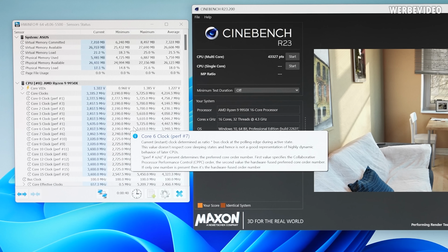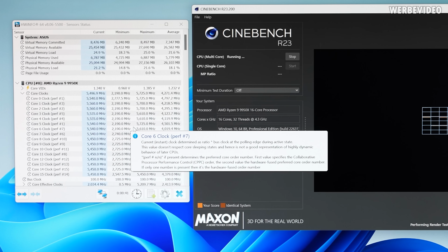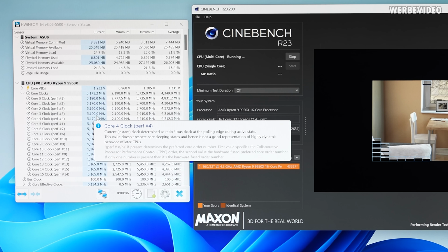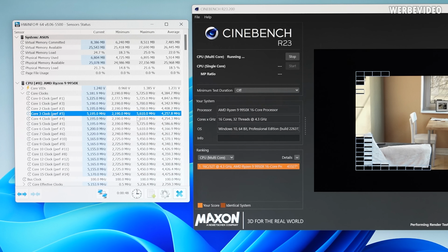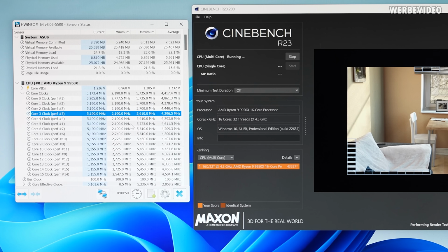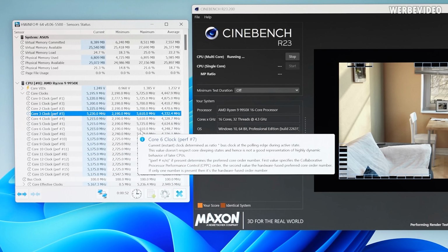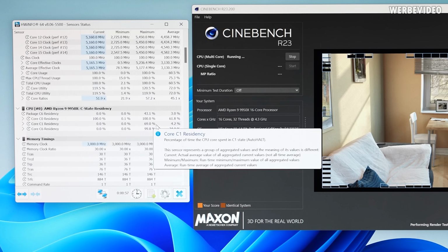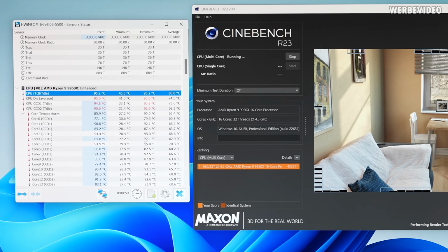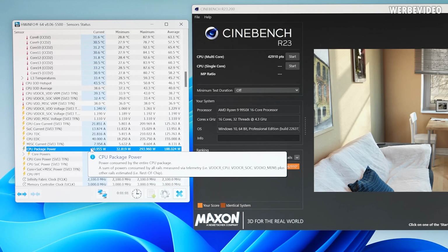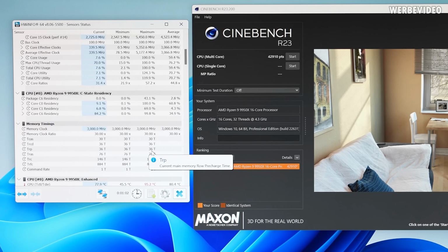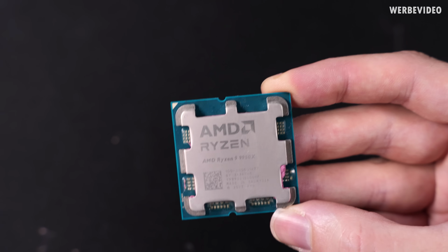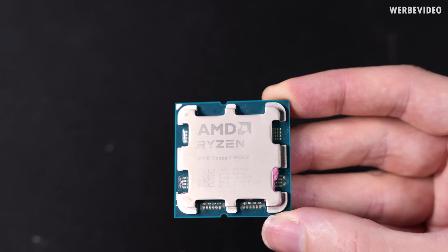And even if I would proceed with manual overclocking, I could fine-tune this a little. So maybe get 50 megahertz to 100 megahertz extra with a slightly lower V-core and adjust the clock a little bit. But that's basically about it. And that's where I just want to start from. That's the starting point, about 95 degrees Celsius with a 360 AIO, just below 300 watts and between 5.1 and 5.2 gigahertz under load. And there we have our 9950X stock condition.